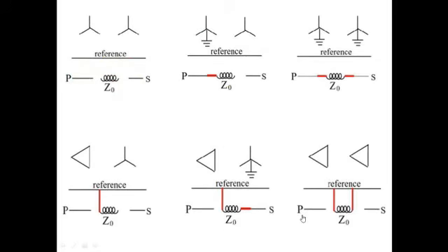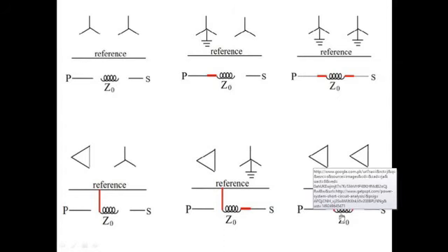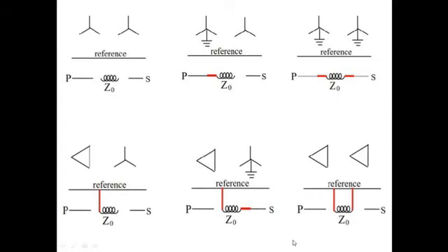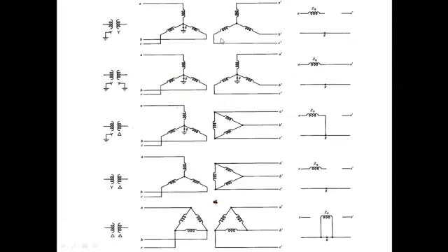Or we can summarize all these. If we have all the discussion, we can summarize in this form. Both are ungrounded, so both are open. One is grounded, so one is grounded, one is open. Both are grounded, both are connected. Similarly, both are ungrounded. Here one is grounded and here both are ungrounded, so both are open. So we can configure this in this slide or in the previous slide. These both configurations are of the same circuit for the zero sequence network.